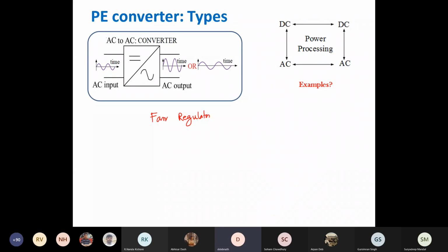And the example you gave, indirectly, in the power electronics domain we call it a solid state transformer. Basically, what we do, we convert AC to DC, then back to AC. You know, the limitation of a transformer is that the output frequency is going to be the same as the input frequency. You cannot change it. Similarly, the output voltage is defined for a given value. Maybe one step up ratio, one step down ratio, that is defined, right? You cannot control it much.